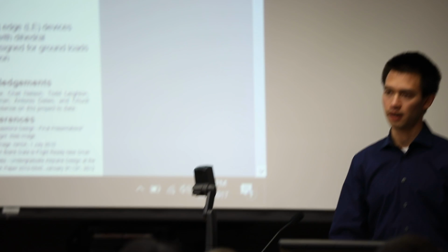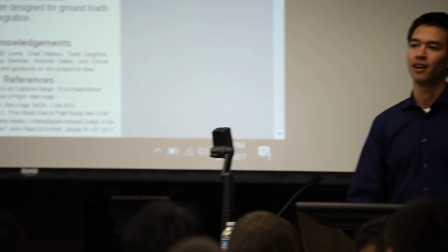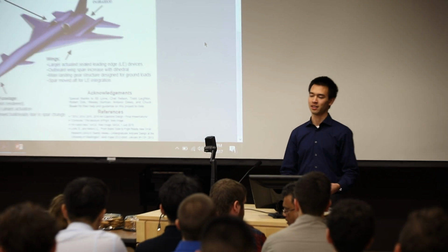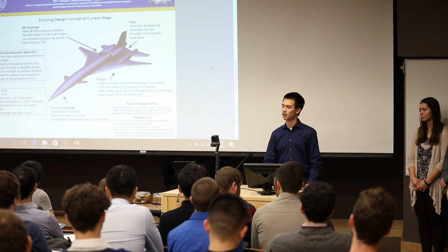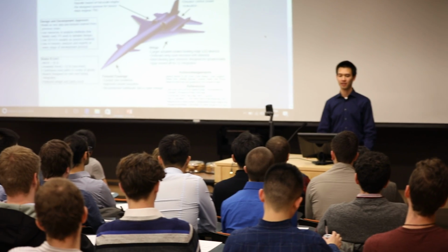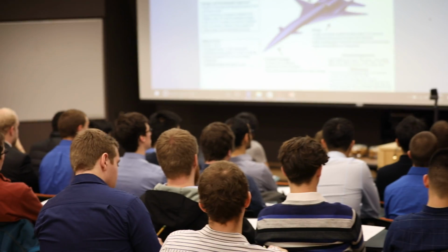So overall, we're looking at the same target max gross weight of 36 pounds with at least 22 pounds of thrust at sea level, which was last year. Overall, we're going to evaluate a complete structural redesign to ensure continuous load paths, beams everywhere designed for wiring and piping integration, and reduce our parts count and weight so that we have a simple model that can be easily constructed in the time constraints and won't have a weight runaway after construction is done.